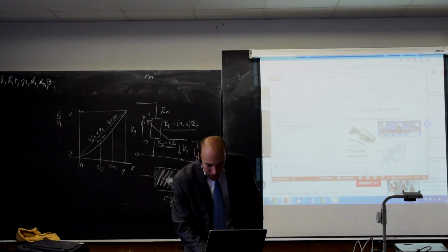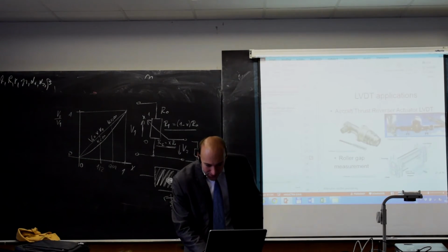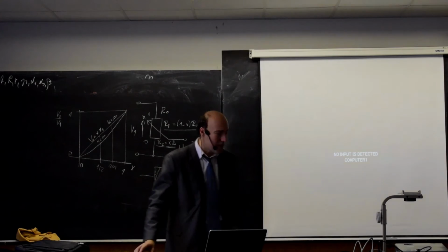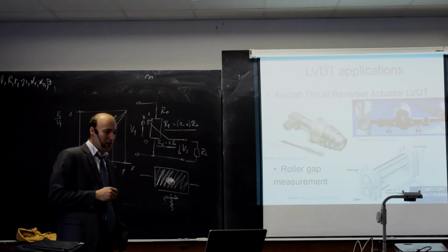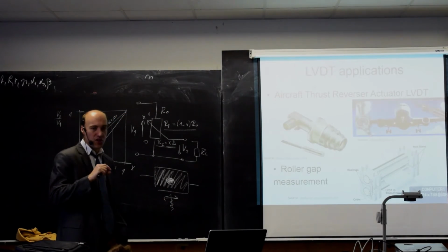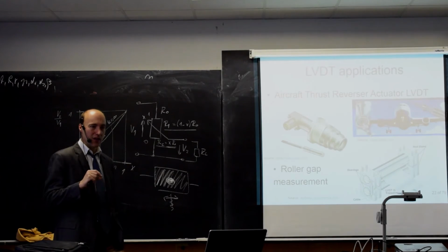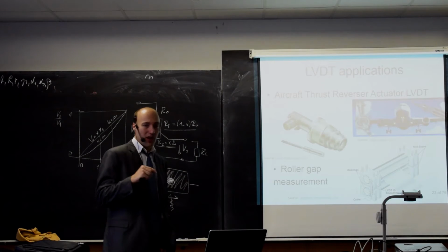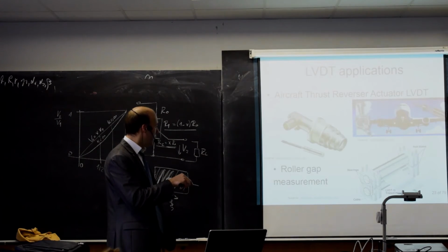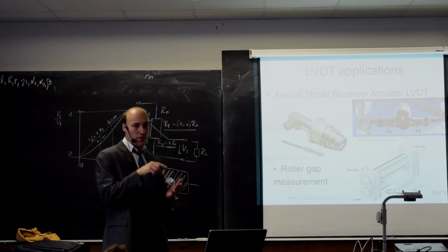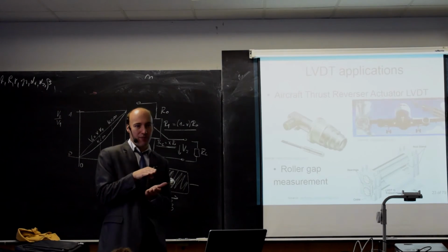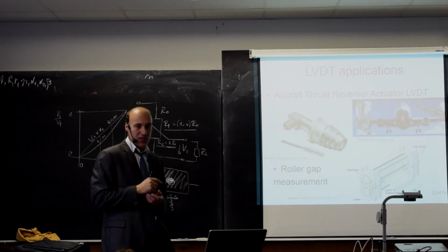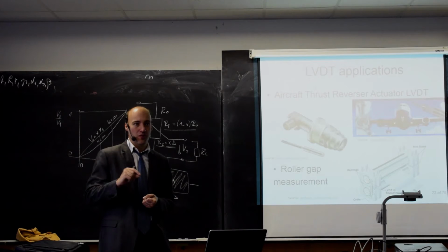Another application for a mechanical engineer: if you produce thin sheets of material like metal or plastic, this is typically done by rolling. So you have two rollers, and you need to very accurately control the gap between those rollers, so we have the desired thickness of the product.